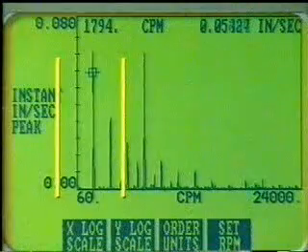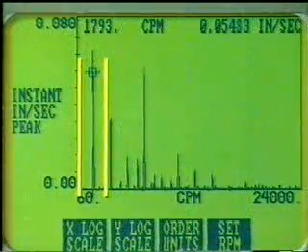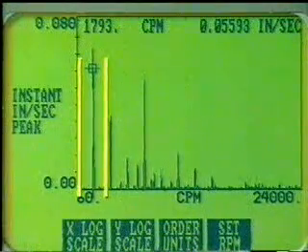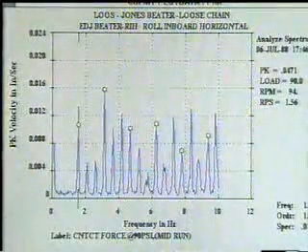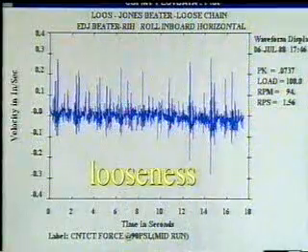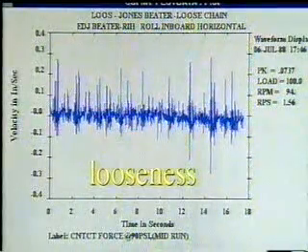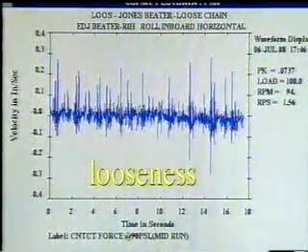During normal phase measurements, if the phase is very unsteady, not simply slowly rotating or staying within a certain window, then check the spectrum for peaks near the 1 times peak and verify that the bandwidth is narrow enough to include only the 1 times peak. Also check for a looseness spectral pattern, that is, multiple harmonics of the turning speed peak. The waveform of a looseness condition will have a very non-repetitive pattern due to the random impacts as the rotor is rattling around in the mountings.